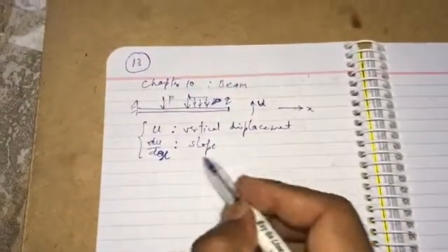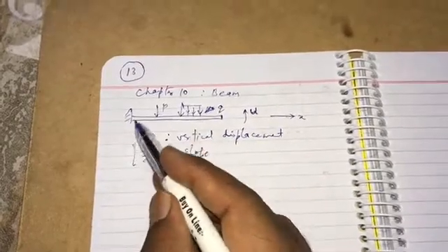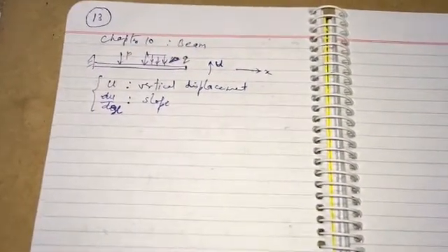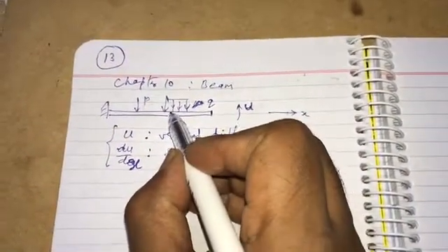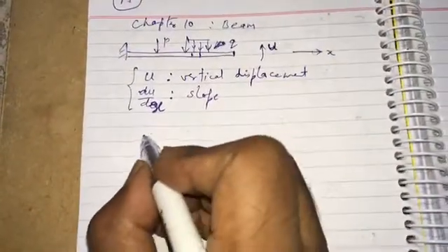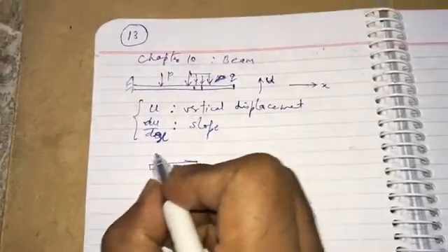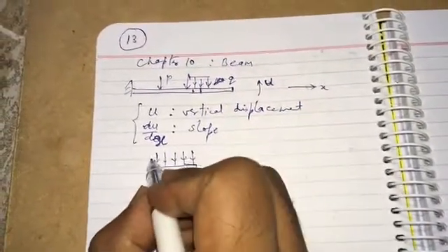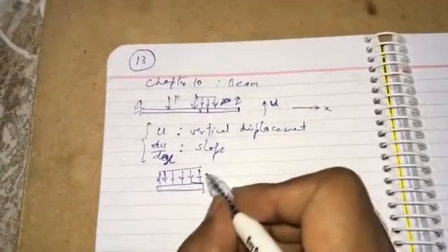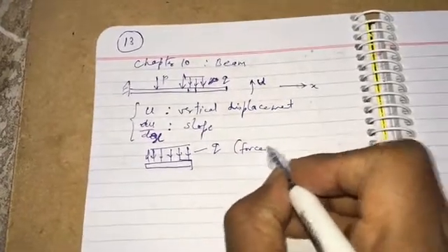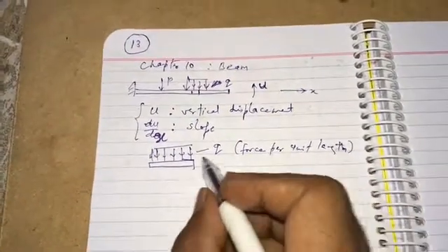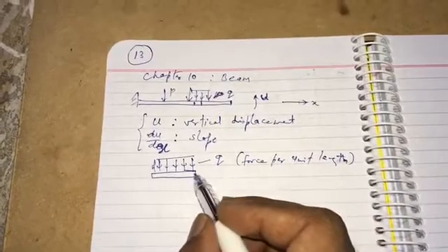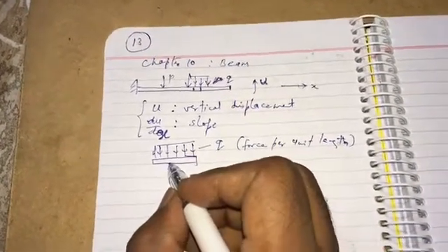If the problem is a beam problem which has to be solved, the first thing we will need is to write the equations. So let's take one small slice from here and draw it here. How will it look? It looks like this. Here is Q, which is the force per unit length. And what kind of force is it? This is the vertical, transverse force applied on the beam. So this is Q. Then we have to apply the other forces.